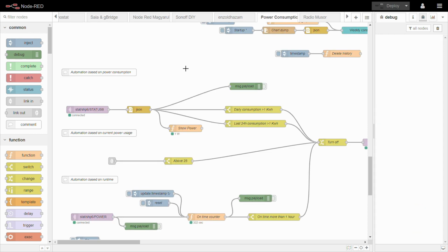And the rest of the automation flow is about looking at the consumption of the device. And in these examples, I'm using the actual consumption, as in kilowatt hours, rather than the power that is being drawn by the device. Because I think we do have a lot of devices which tend to go for a peak. Like, as I said previously, you have a pump. When it starts, let's say, moving fluid around, it would definitely have a peak, and then there could be other reasons why there is a sudden surge in the beginning when you switch something on.